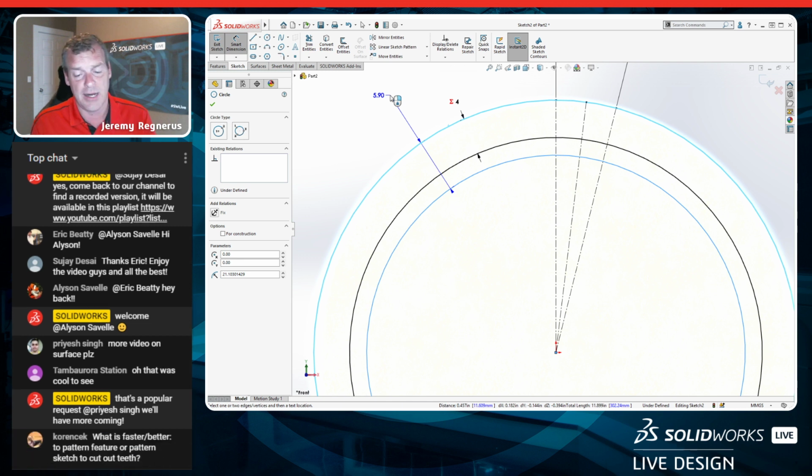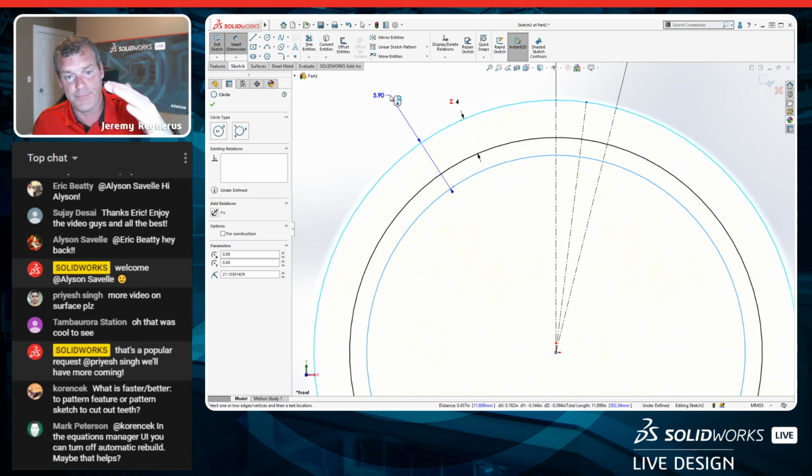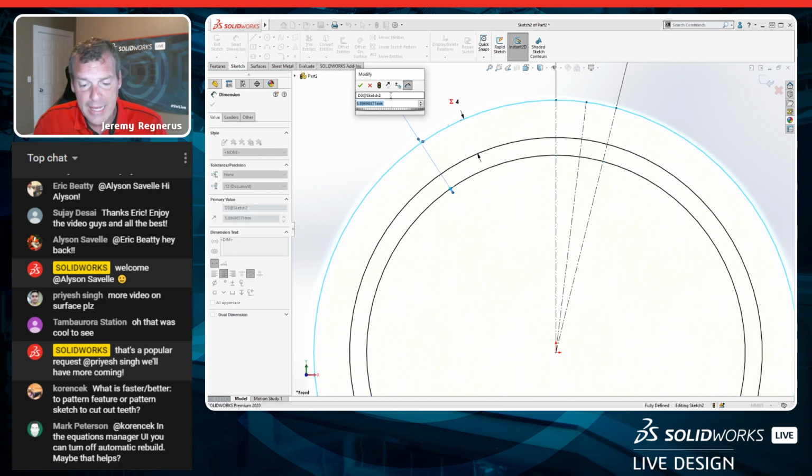In the case of the metric module system, the values that I've seen say that if the module value is coarser, equal to or greater than 1.25, the clearance on the bottom should be 0.25 of the module, otherwise 0.24. Notice the value that I'm doing here, though. I'm doing the hole depth, not just the clearance at the bottom. So I'm going to go ahead here and we're going to create this.